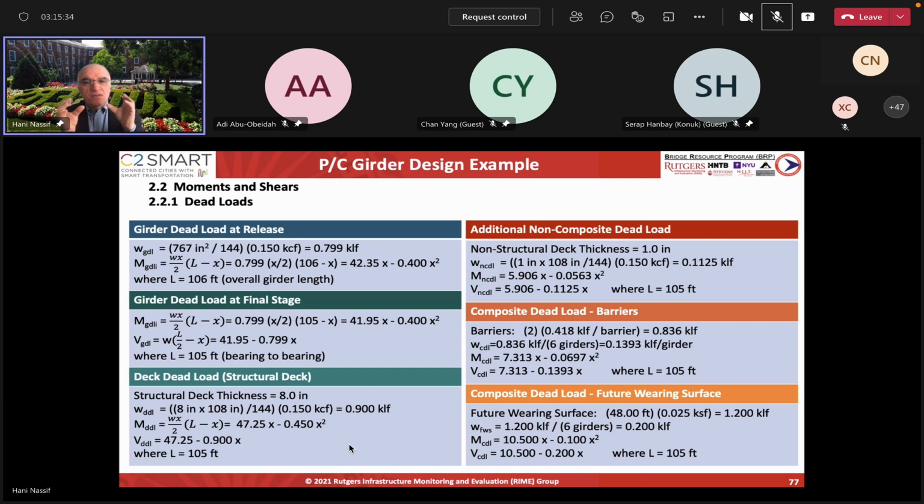it will camber up, the pre-tension. So you have to make sure that the stress on the top of the girder in tension is less than the allowable, because if it's not, then it might crack. You don't want it to be cracked. And the same thing in compression on the bottom at service. So there are 4 allowable stresses: 2 at service, and 2 at transfer or initial. And you have to make sure that you satisfy each of those. This is how you make sure your design is adequate, okay?